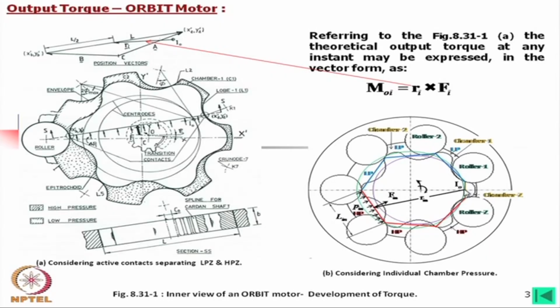Now, obviously, the instantaneous point of rotation of the equivalent drum is now situated on the x axis. This whole body, the star, is revolving around this axis in the anti-clockwise direction, whereas this body itself is rotating in the clockwise direction. So, output will be clockwise looking from this side. Okay.